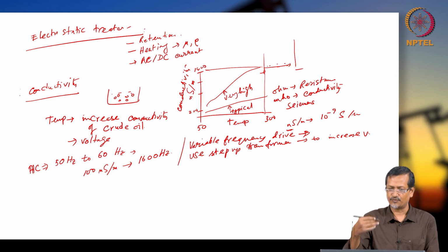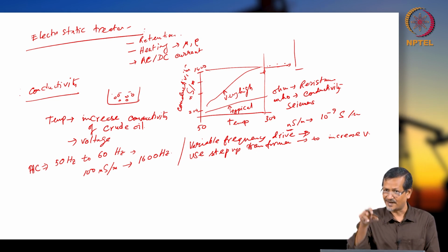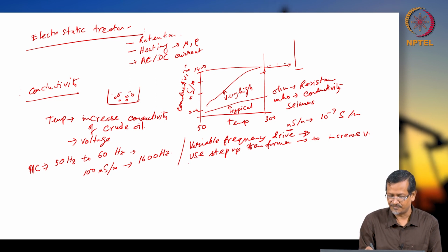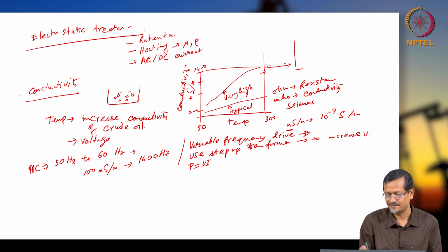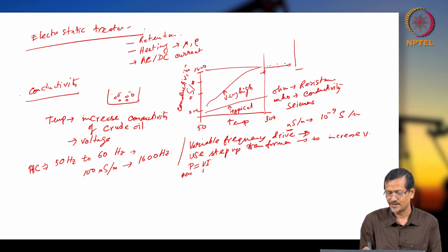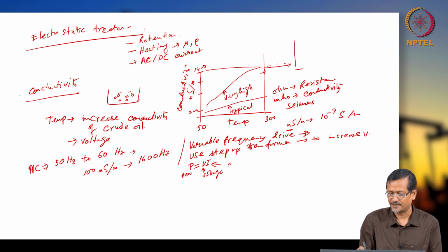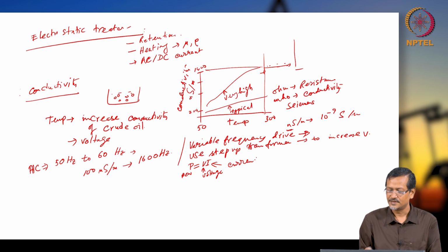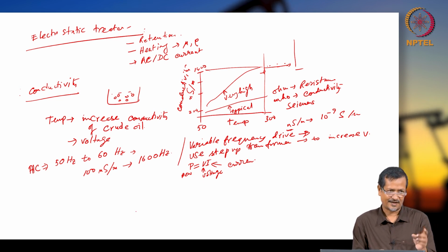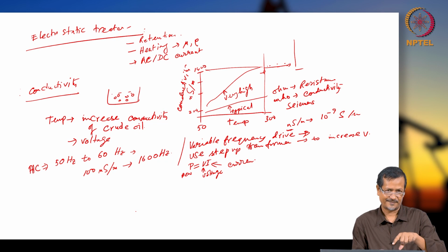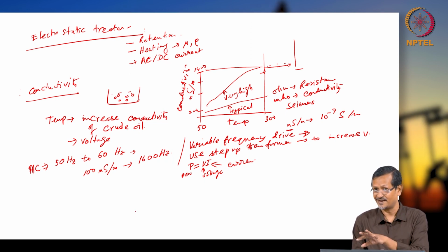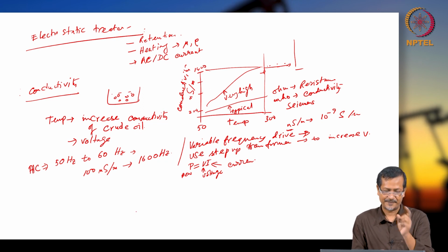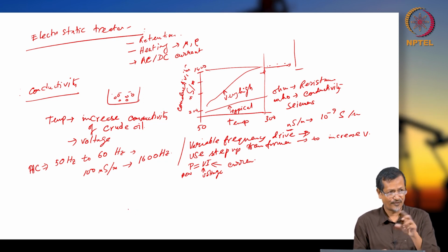When you are increasing voltage with power fixed, your current will be going down, right? So how can I say that? P equals V times I: power, voltage, current. If you are changing voltage and power is fixed, that means current is dropping. Whenever we use the terms step up and step down, we are not using them for current, we are using them for voltage only.